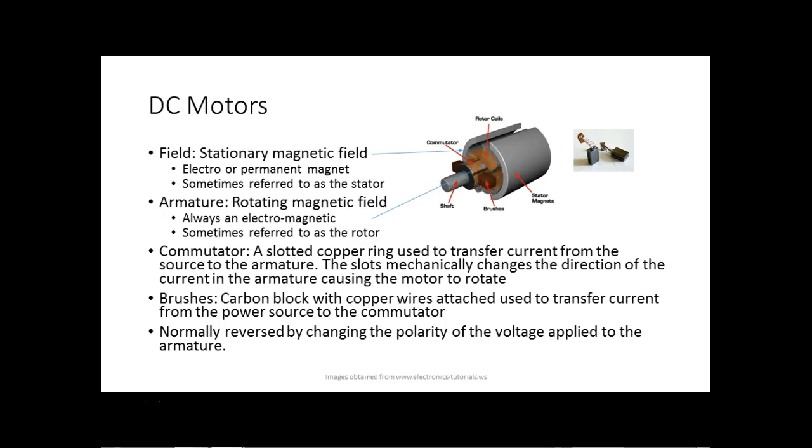So how do electrical motors operate? Well, they operate on the principle of repulsion and attraction of magnetic fields. At least one field's got to be electrical. What advantage does an electromagnet have over a permanent magnet? We can turn it off and we can turn it on, and we can also shift it, right? You understand? So I can change the connection and actually make the north pole the south pole and the south pole the north pole. So that's basically what we're trying to do with the motor here.